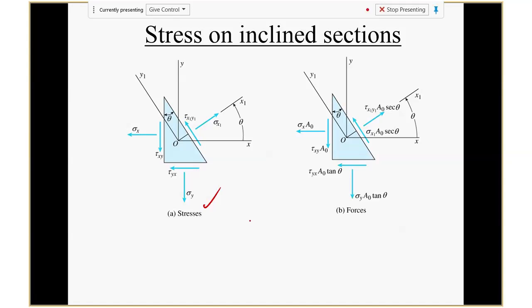So you can use sigma Fx equals 0, sigma Fy equals 0. Or you can use sigma F theta equals 0, and then sigma F theta plus 90 also equals 0. You can use either set of equations. They all should be true, because in equilibrium, in any direction, the forces added together must be 0. So you can use either the top two or the bottom two, whichever you feel more comfortable with, or whichever quickly gives you the answer.